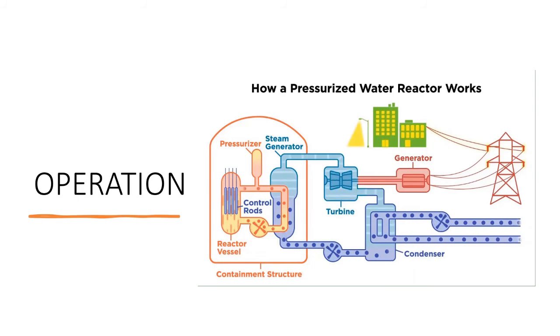As for the pressurized water reactor, the process is almost the same as the boiling water reactor. The difference is that in a pressurized water reactor, process water circulates in the pipe system of two separate process circuits, which are the primary circuit and the secondary circuit. The reactor coolant pump circulates water in the primary circuit. Pressure is increased in the primary circuit with a pressurizer to a level where the water does not boil. In the reactor, the primary circuit's water is heated with the heat generated in the fission reaction.